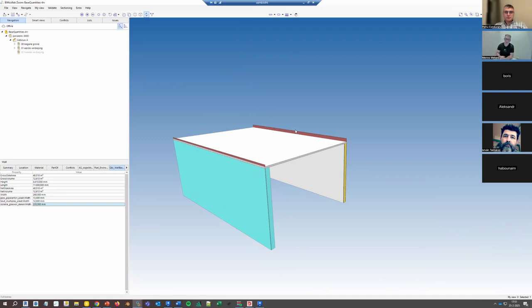Does it make sense what I exported? And also reference your Revit schedules, because in Revit you also have the quantities. You can easily create a schedule that says this is the square meters of wall that I have. And in my IFC viewer, I can also get a report and just compare them, to see whether they match or not.